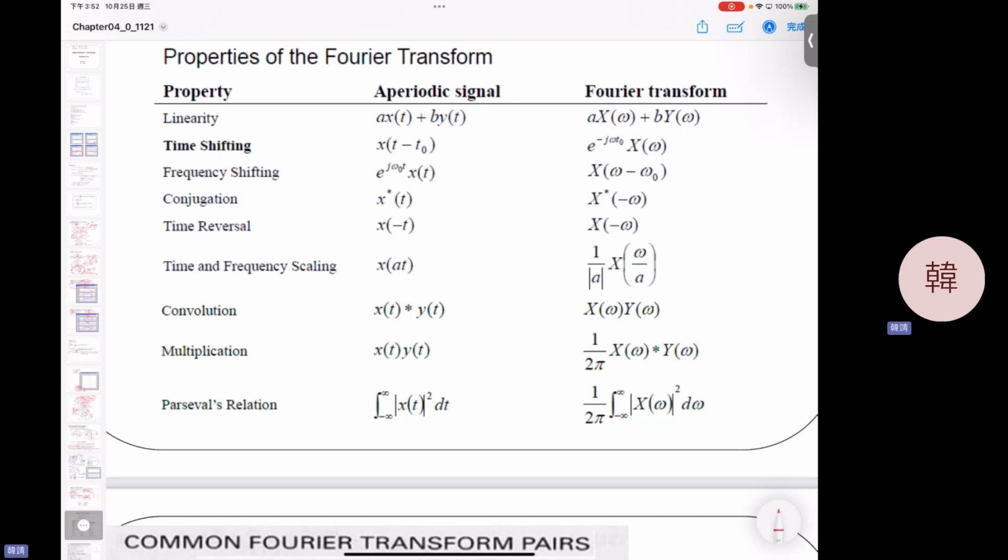In chapter 4, at the beginning they just show you this example, but I will explain why. Because they multiply by the comb function, they are sampling your image. And what happens in the frequency domain is your image spectrum is convolved with this sampling function, Y(omega) there, if y is the comb function. Also you have to know how you sample it, and it depends on your sampling time, your sampling spatial resolution.